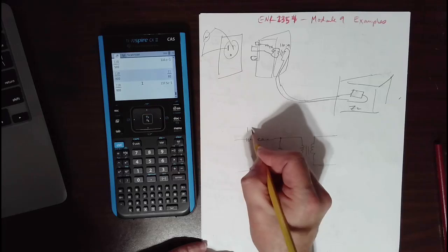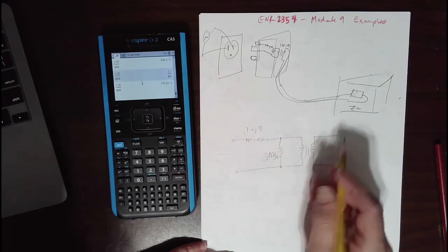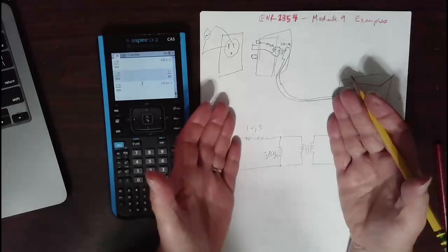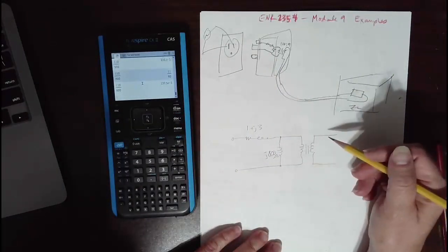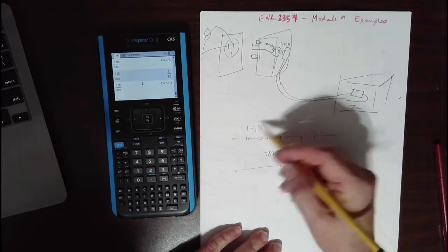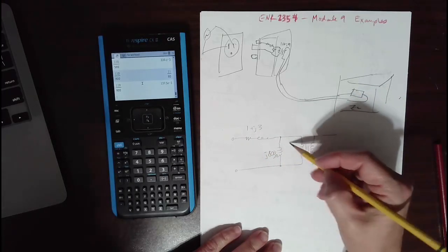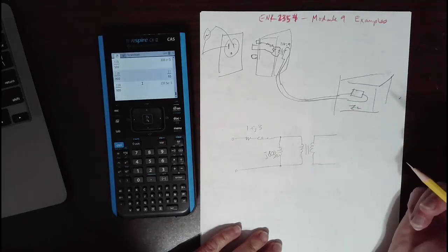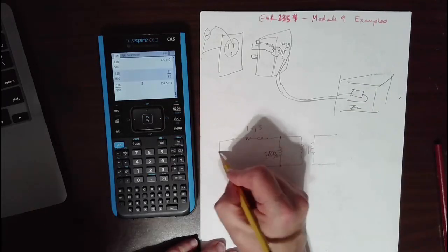And we'll have just some resistance and some inductance to represent the coils. So this is a model of a more realistic transformer that would have the ideal transformer, which is lossless, and then we have the inductors and resistors, and some models will have another resistor in here too, to model the losses in the transformer itself.